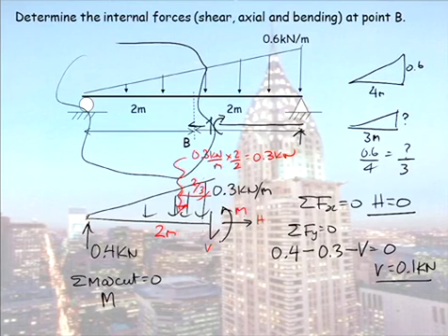And can you see, if now the support is on this side, the way I've drawn that moment is still causing a happy face. So that's how clockwise on the left, anti-clockwise on the right are a positive bending moment. However, when we come and consider equilibrium, we use our Cartesian coordinates, where anti-clockwise is positive. So in this case, my moment is positive. If I was considering my other free body diagram, I would say it was minus M. But the final value for M I would get would be a positive value.